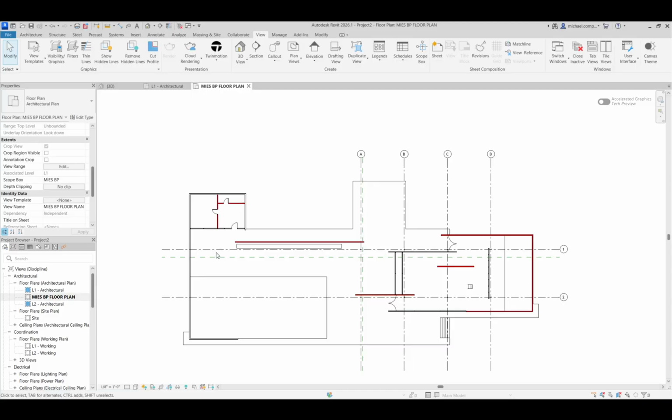So when I say cut, what I mean is Revit is cutting this model at 3 feet above the first level, or level one, or the first floor, if that's how you're oriented. But that's the section, so that's what's being cut. And so for architectural presentation plans, we like those cuts to be pocheted. In this case, I'm using red to highlight that.